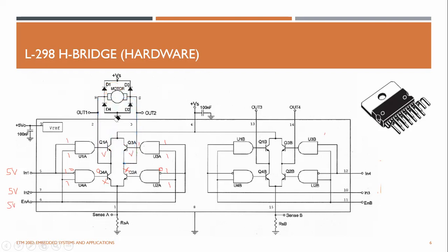So even if the motor is running the other way, the same principle happens. Only a different diode will be used in the application: this transistor and maybe D1 will be turned on, keeping the motor current circulating and helping to disappear the magnetic field and stop the motor real fast.